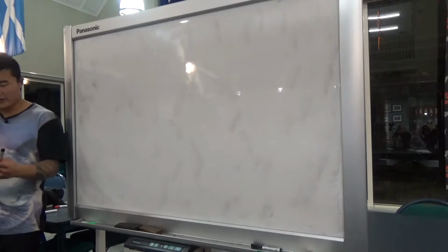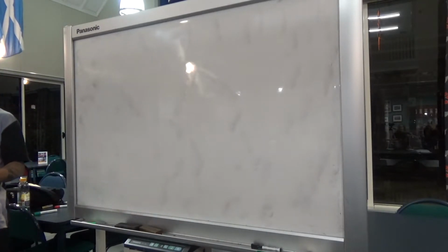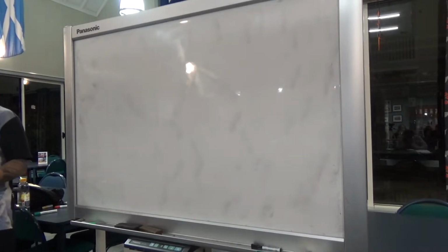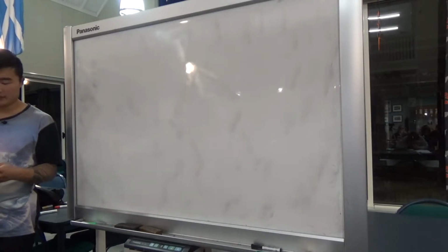Six, 5 identical cubes of lead are stacked in a single column on a table surface to make a tower. Each cube has sides which are 44 millimeters long. What's the gauge pressure between the undersurface of the tower and the surface of the table?